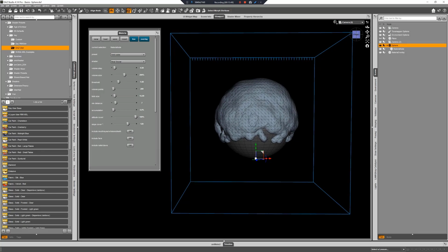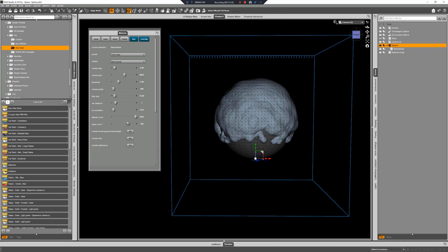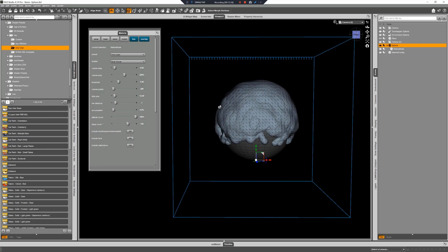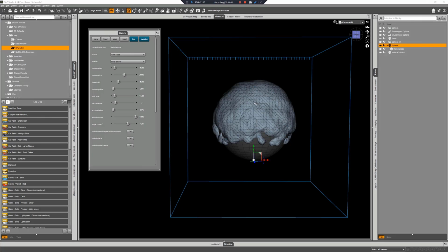Okay, so now we are going to take a look at the slope cover before, then the altitude cover. So the slope cover basically allows Materia to produce geometry where the angle formed with a specific point on the object surface and an up vector is within the value specified in the interface. So here I was drawing the up vector, and a series of normal vectors hitting the sphere surface. A normal vector is just a ray that hits the surface, forming a perpendicular, forming a 90 degrees angle